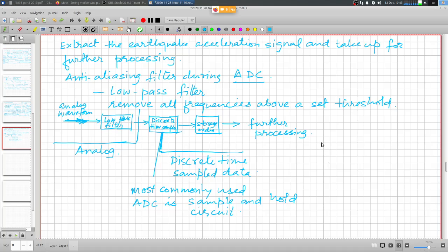Right, so what is done is you have the quantization levels. Whatever the signal is that happens between quantized levels, it is held at that digital value, at that constant value. In the next time interval, it may be at another quantized level, and so on. So what you get is a set of points where the signal is held constant over the time interval of sampling.